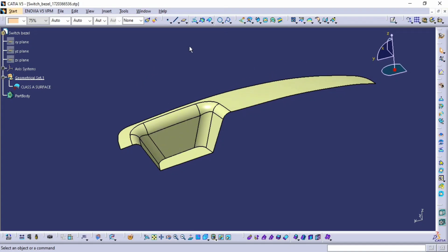There are many ways that we can create a tooling axis. For example, we can make a sketch at this point, and that sketch will act as our tooling axis. Or else we can directly choose the line command from here itself, and that can act as a tooling axis. I told you one golden rule regarding the tooling axis: it should cover all the draft faces.